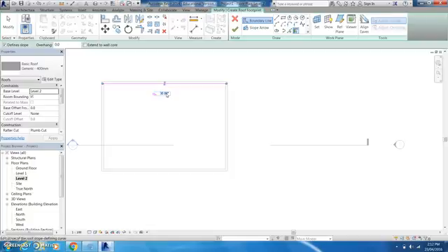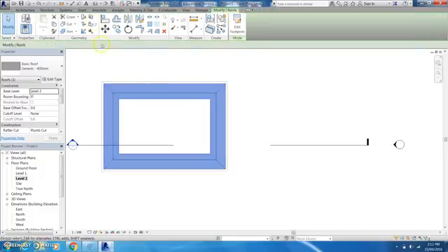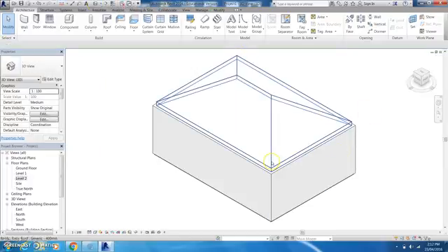That means that the wall will lean from there to the center at 30 degrees. So I'm just going to draw in quickly a roof that would all lean in at 30 degrees, and we can just have a quick look at that. Slope, edit, and there it is. So there's our roof that we've drawn in at 30 degrees.